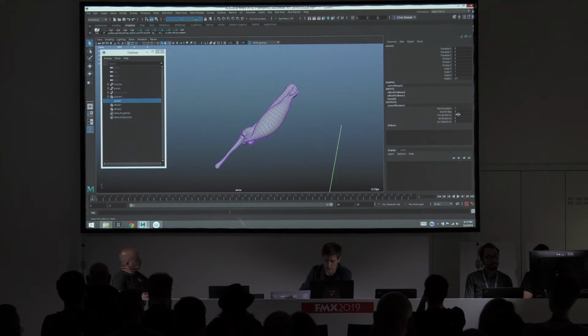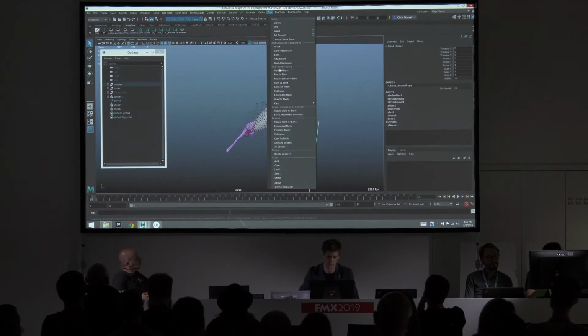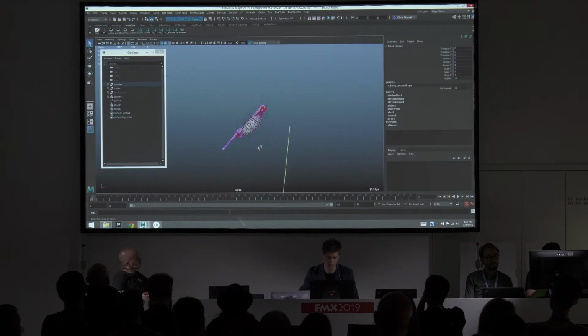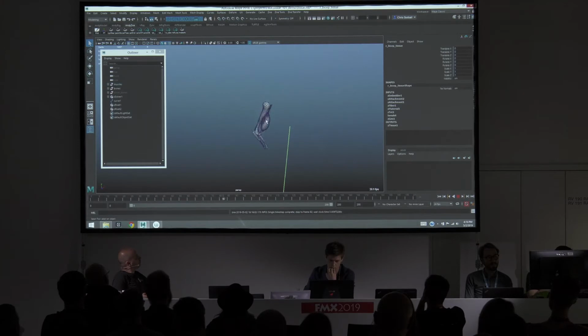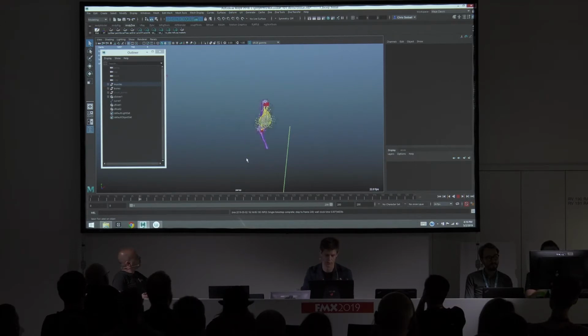Or velocity or acceleration. I'm just going to stick with position now, but I'm going to make it 4 times more sensitive. So I'm changing that to 4. And then clear the cache. And hopefully now we'll see the muscle firing happen when there's actually a few more frames to this sim. So you can see it sort of changing color when the elbow bends. It's forcing the muscle to contract.